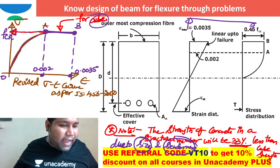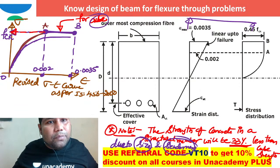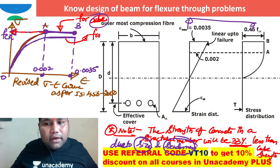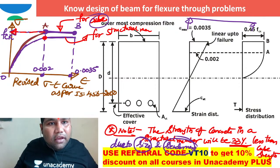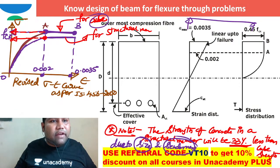This is how the curve will come into picture. So what is this curve called? I can say clearly, this is the curve for structural member. What is the failure stress for the structural member? That failure stress will be less than FCK. And what is that value? This value is FCK by the factor of safety for shape and size effect.